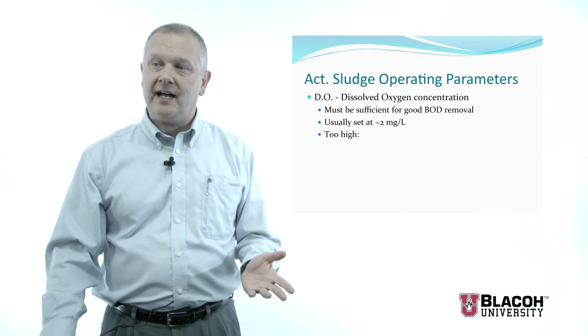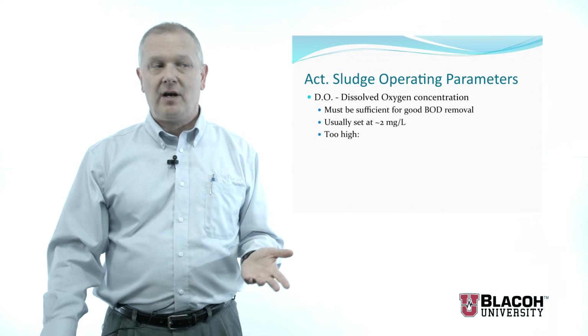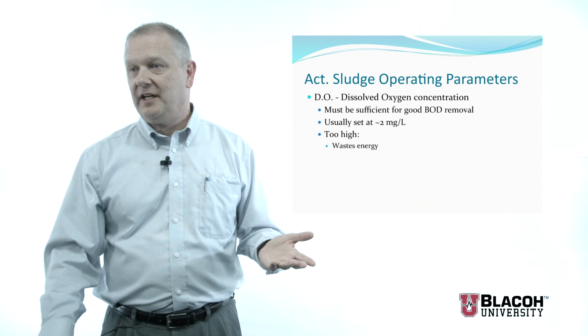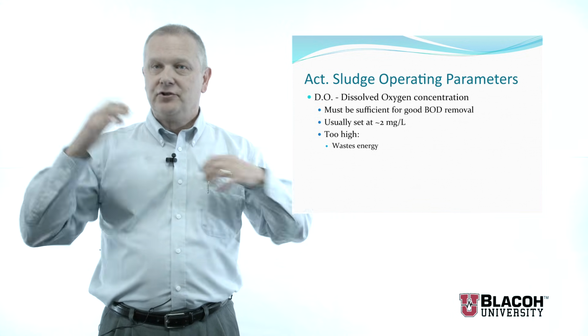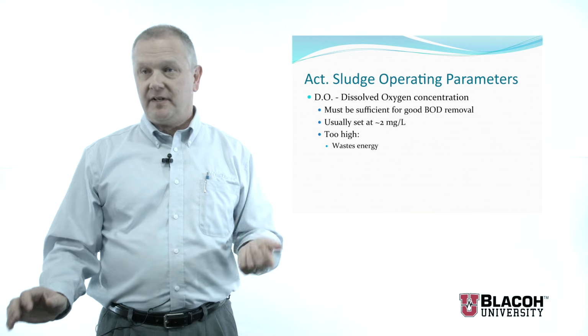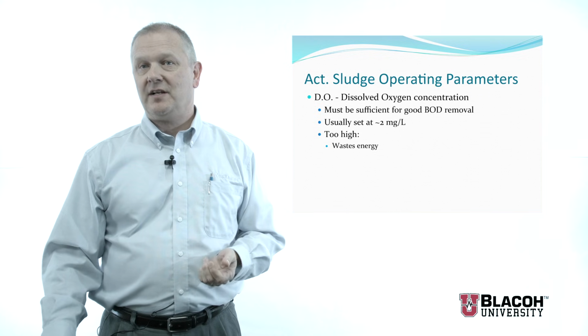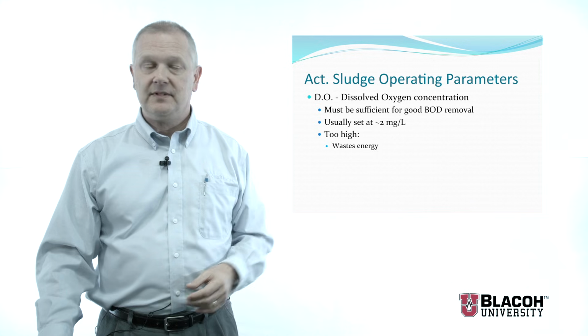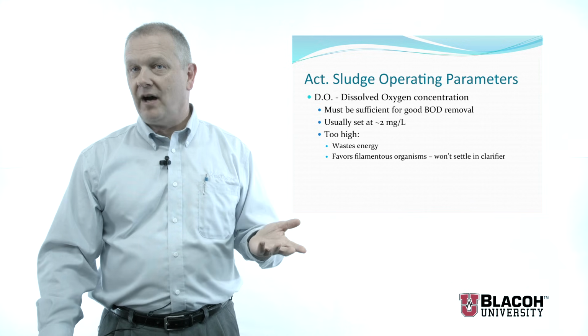If you set it too high, there's a couple problems. First of all, it wastes energy. You're spending a lot of energy churning up the liquid or blowing air into the liquid, and that's a very expensive part of the waste treatment process, this aeration. And so you don't want to set it too high.